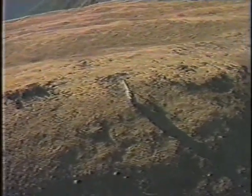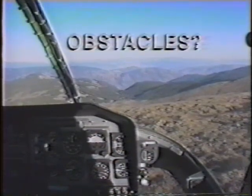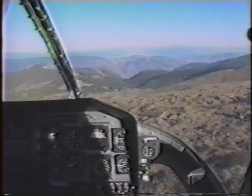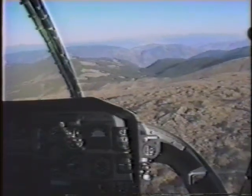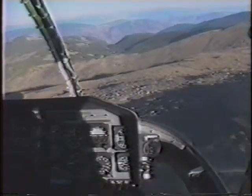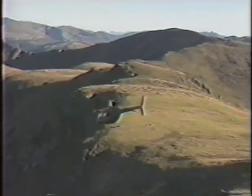As we talked about earlier, the departure is also designed to give you every extra advantage in this challenging environment. After you've done all your ground checks and wind checks, review all the variables along your departure path. Then, slowly pull into a low hover, watching for any evidence of instability or problems, and ease into forward flight toward the drop-off. That's the standard recce approach, landing, and departure for any piece of terrain. But each topographical feature carries a few of its own tricky idiosyncrasies.